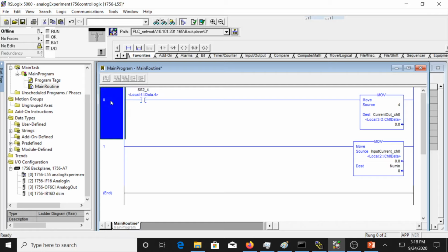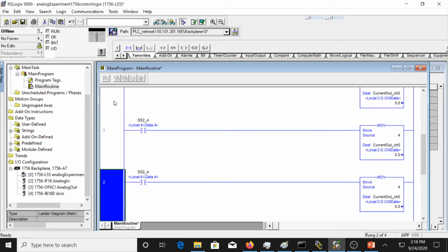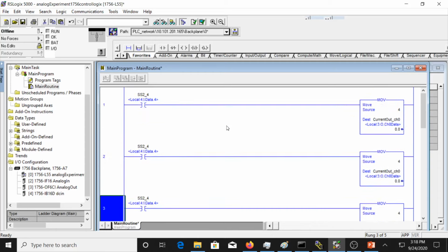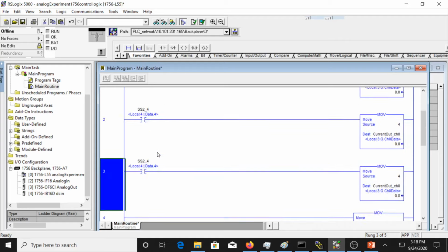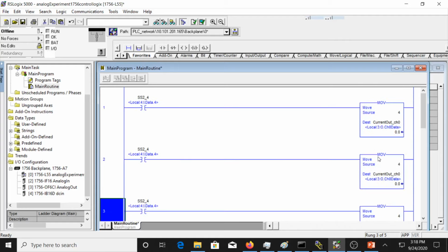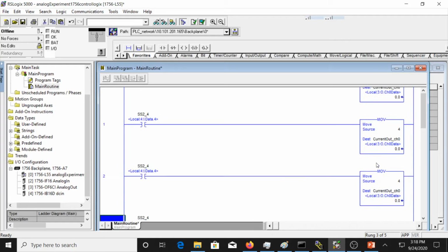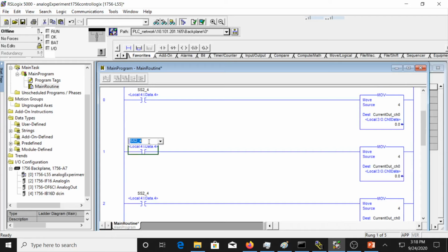And then I'm going to come over here, and while I've got the number of the rung highlighted, I'm going to Control-C, Control-V, and paste this 4 times. Okay, so I've pasted. Did I do 4? Let's see, 1, 2, 3, 4. So it's a 4 selector. I want 4 of these. And so this is going to be number 5, and I'm going to output 8.